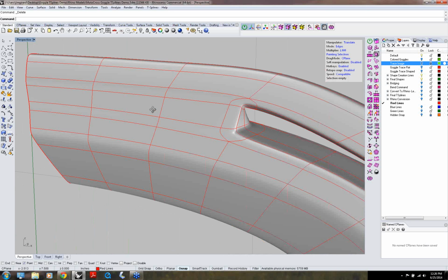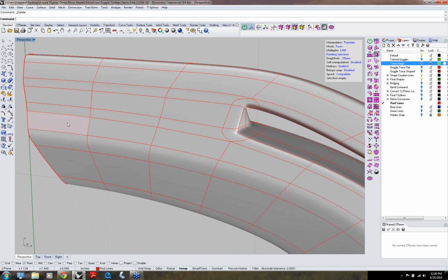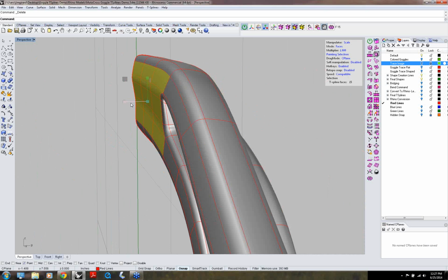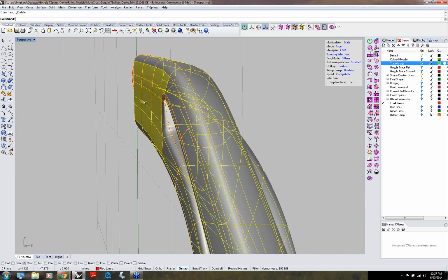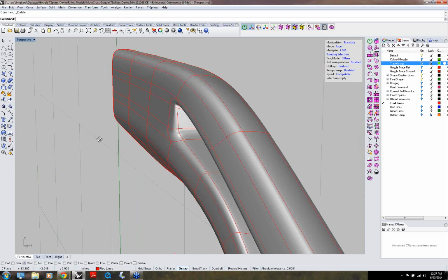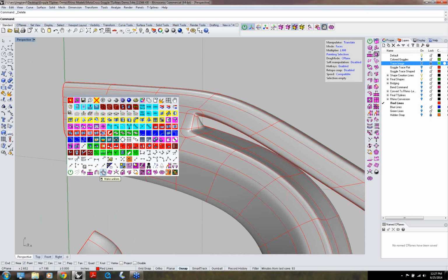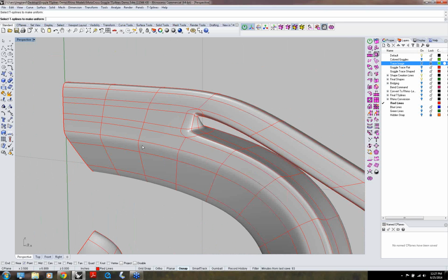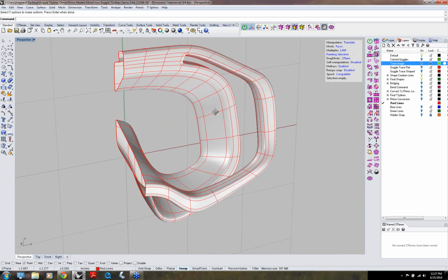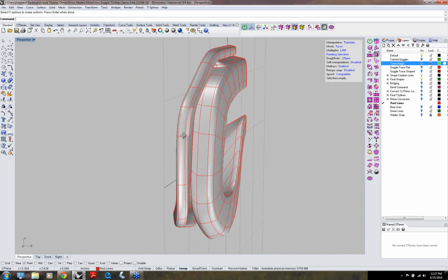So the neat thing you can do is go to your command here, and I have it still invoked with the painting command, and you can go R, and you can just really pull these surfaces right into place. Pull it out a little bit, and then again, I always try to make uniform to relax those surfaces, and now you can see where I've bridged those surfaces together.